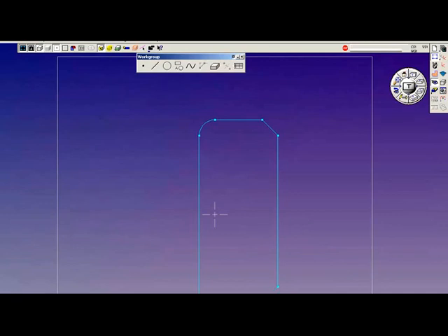This time it's measured along the depth from here to here, to the imaginary point. And one more corner, defined along its length. 0.5, same value. This one is shorter than the other two because it's 0.5 from here to here. So my suggestion would be to draw your geometry sharp cornered, and then you can put in your automatic chamfers and radiuses as you see fit, as you need them.